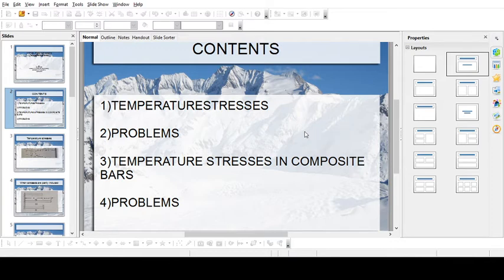That part is simply delta. So here the total elongation or this compression is simply delta L, means this line. Okay. So what is this value? It is simply total L alpha T minus delta. So L alpha T minus delta.